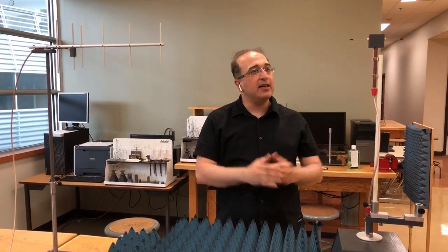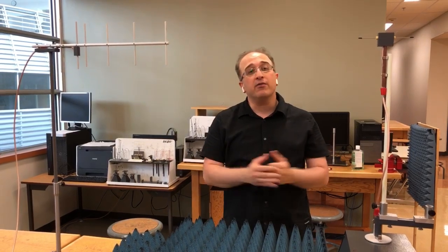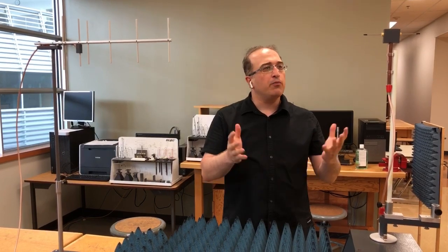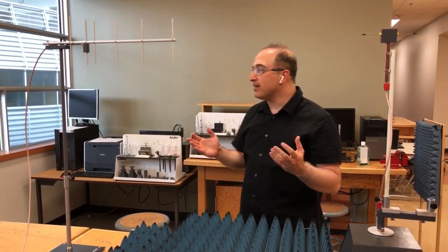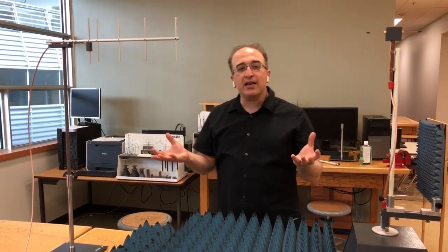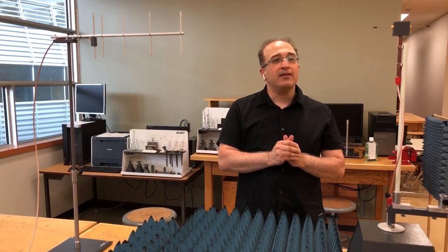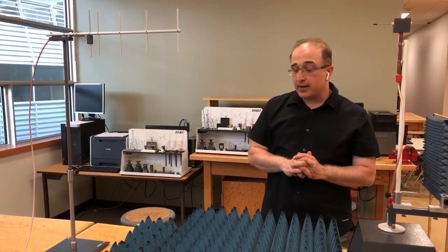But that's not the case in practice. You're gonna still receive signal, and then we're gonna call that cross-pole E-plane pattern. So I'm gonna start the measurement, and we're gonna look at the radiation pattern. If everything is correct, it's expected that the x-pole E-plane pattern would be below co-pole adjacent E-plane pattern.